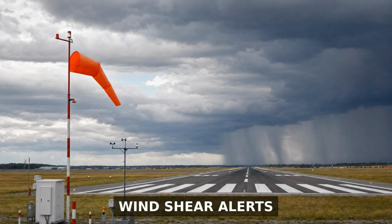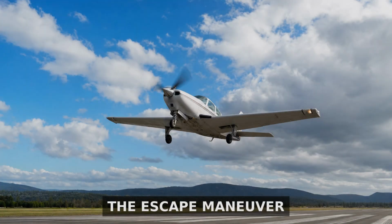Airports use low-level wind shear alert systems to detect microbursts. Listen for wind shear reports from air traffic control and pilot reports on the frequency. If a microburst is reported on or near the approach, the only correct decision is to go around, wait, or divert.